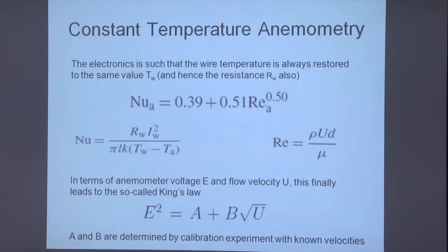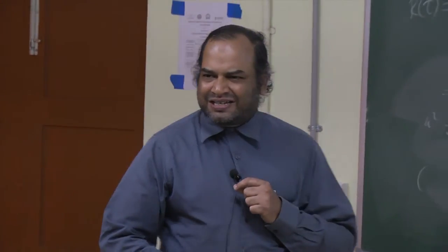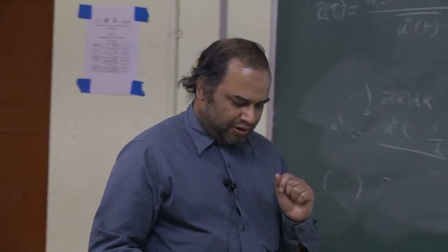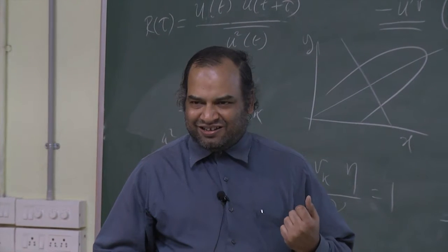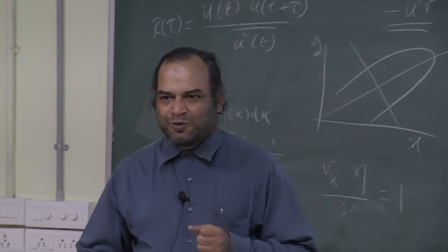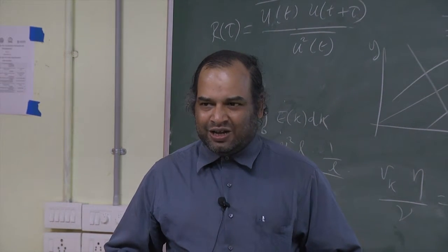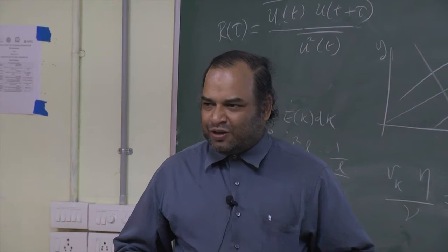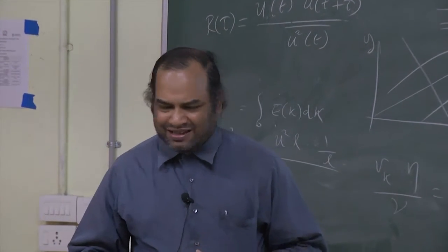But that's easier said than done, I must say, because I must tell you right away, the hot wire is a very whimsical instrument. It has a mind of its own. Be warned, don't take the hot wire for granted. Despite using hot wires for almost 60, 70 years now, people would say that though we use it, it's more of an art than a science at some level, because it's very whimsical. So there are many practical dirty tricks if you are going to be using it. For instance, I always tell my students making measurements with hot wire, don't switch it off for heaven's sake. There will be calibration drifts and so on. Whereas if you keep it on for a long time, it turns out that the behavior could be very good sometimes, and many people have found this. There are many tricks like that.